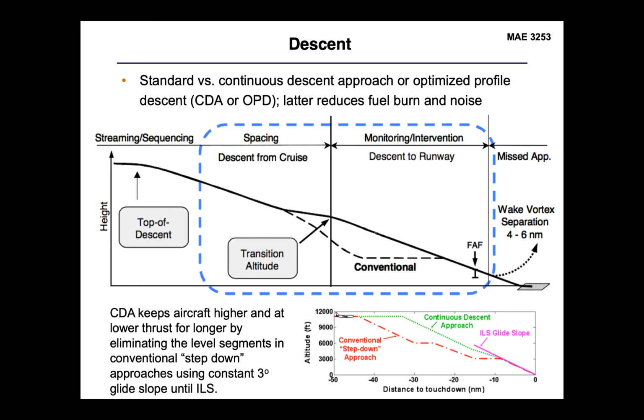Now, as I mentioned, there is a lot going on in the descent. Just so that you're aware of what's happening, for most aircraft, as you're coming into the pattern, this is going to be dictated either by looking at your directory that's going to tell you whether you're going to be coming into a right-hand or a left-hand pattern, or whether you're going to be guided in by air traffic control. You'll have a certain sequence that you'll start into for your landing phase, where given a certain glide slope, you'll be able to determine what that distance required needs to be to get you from that entrance into your glide slope to touchdown. This will often be dictated by other traffic in the area, making sure that you have safe separation between your aircraft and the aircraft that you're following, and then, of course, the aircraft that's following you as well.